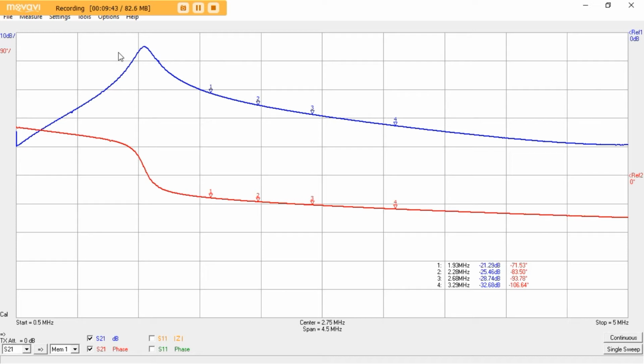Now, interestingly enough, we see that we have quite significantly changed this transmission gain characteristic. I'm going to use marker 2 to move to the peak. This previously was at 2.28 megacycles, and that has now shifted down to 1.44 megacycles. So there's a big shift down in frequency, as we have loaded the top of the Tesla coil.